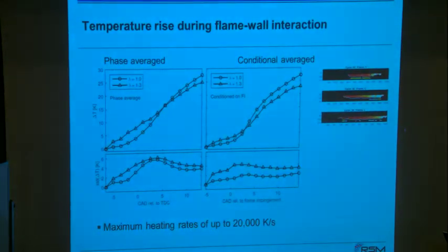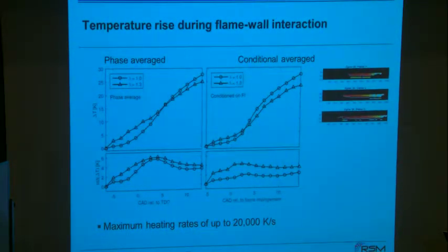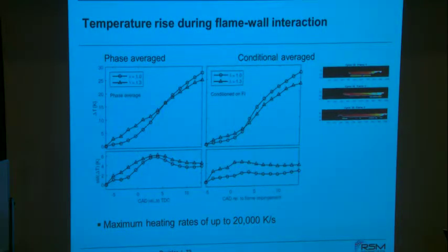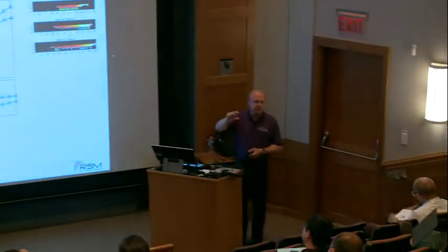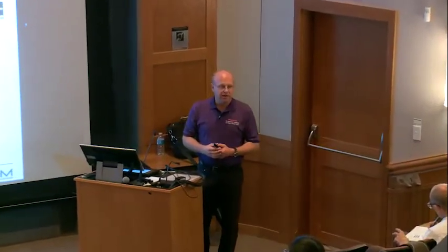You should not maybe do it with 10 cycles. That's too little. So the best way to do that, a general answer again, is not good. What you should do is take initially a large number of realizations, and then you look for the convergence of your statistical moments. So you calculate the mean value, let's say with arbitrarily chosen values. You start with 10, then go to 100, then to 1,000, and look at how your mean value converges. And the same you should do for the RMS value. And then it's up to you to decide which statistical precision you want to have.